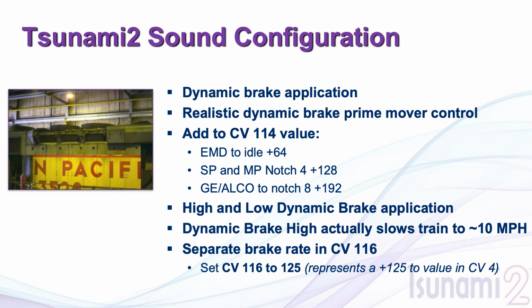Now, that energy has to be dissipated somewhere. And so up here in the dynamic brake grid, you have a bank of resistors. This is where that energy is dissipated, and it goes through the resistors and turns into heat. And that heat has to be dissipated. And so you have the dynamic brake grids up here. You have a few extra fans. So the sound you actually hear when you press the F4 is the sound of the dynamic brake fan as it's blowing air across the resistor grid.